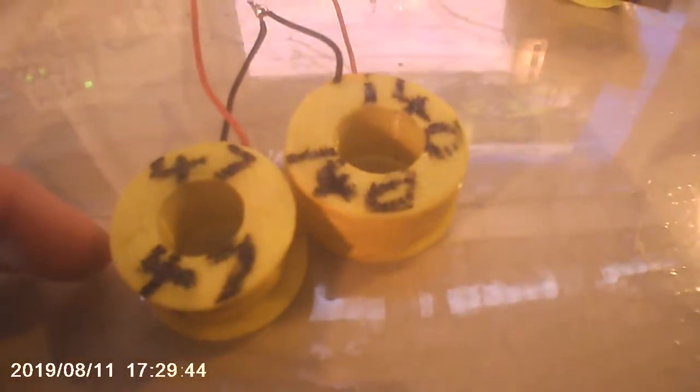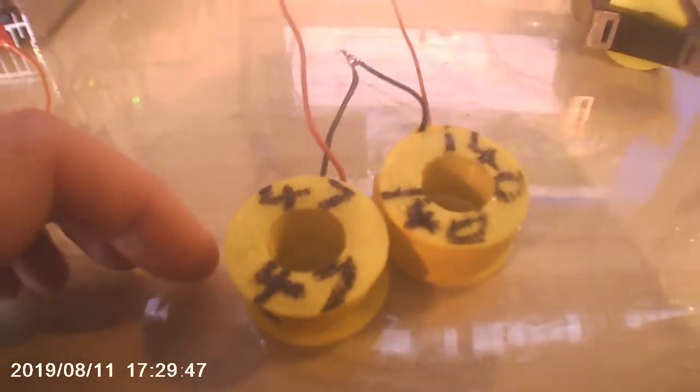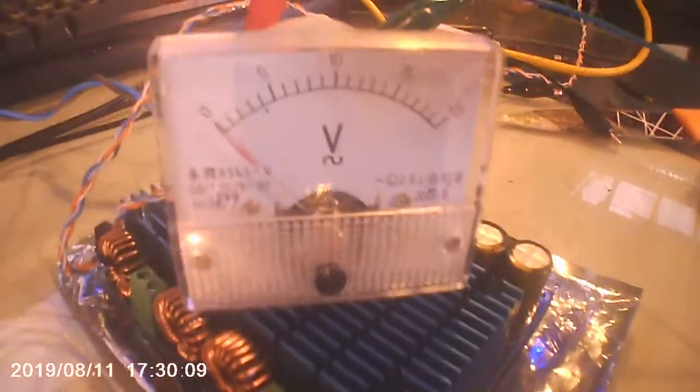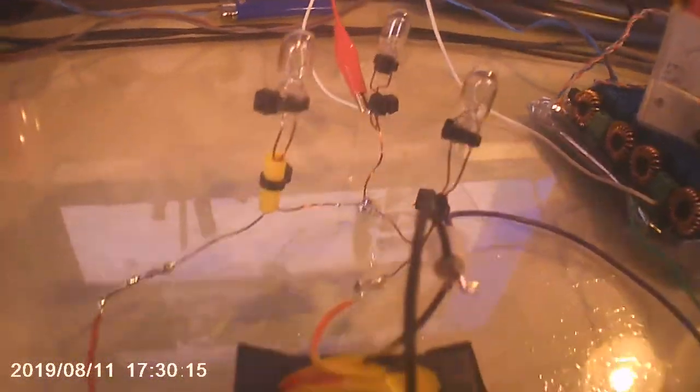the coils I just showed you were low resistance, 50 ohms and 150 ohms. Now that worked quite well because you can actually push some current through there. This set I made a couple of days ago and have been testing, trying to get them working. This is about 360 ohms and 120 ohms. So only about 20% of what our other boy was using. But even at 30 volts, I can't push enough current through the circuit to get any light at all. And nothing on the frequency sweep.